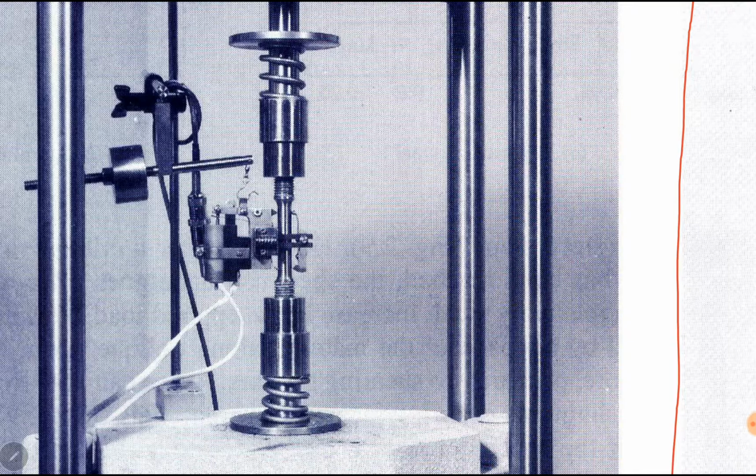Okay. We move forward. This diagram shows stress strain curve for iron and different grades of steel. The first one is, for example, for pure iron, and then carbon steel A36, then high strength low alloy steel A992, then quenched tempered alloy steel A709. We can see for all of them the yield strength and the ultimate strength are different.